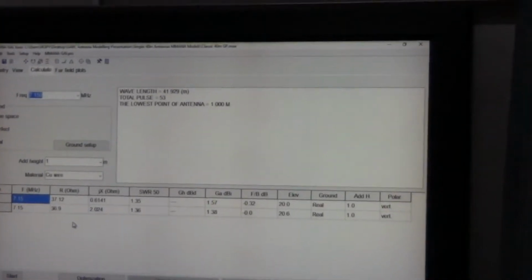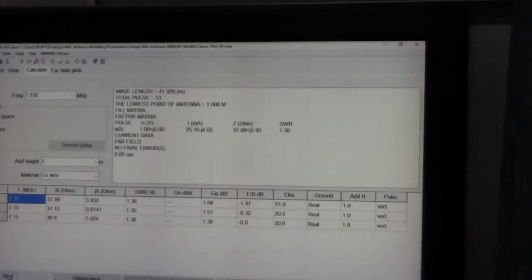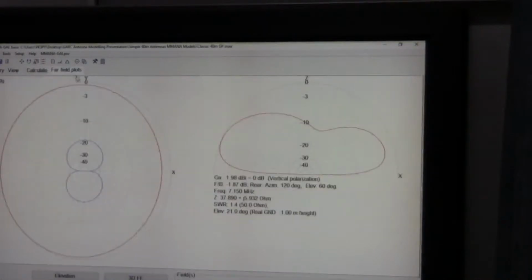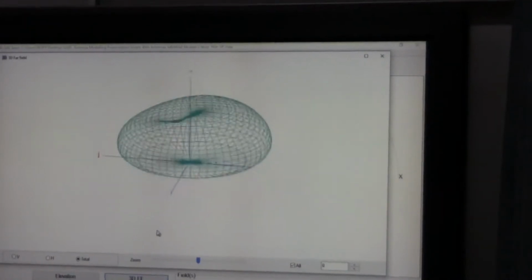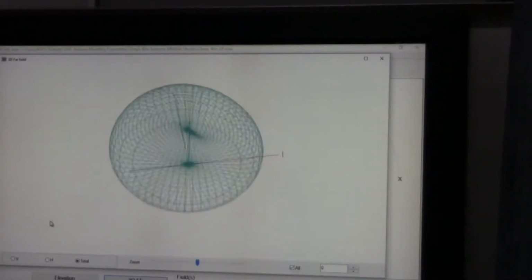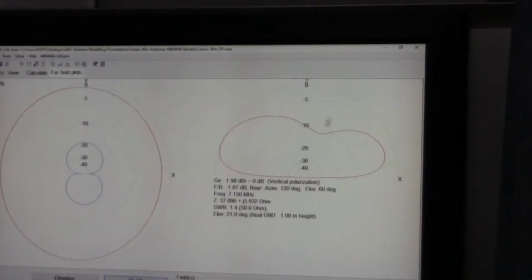Impedance changes. Quite a lot actually. Because now we haven't got cancellation of the horizontal radiation of that remaining radial. Still a long way down at that angle, but when we look at it, it's sort of distorted the pattern a little bit. But still, essentially, not very different from what we have as a perfect ground plane.